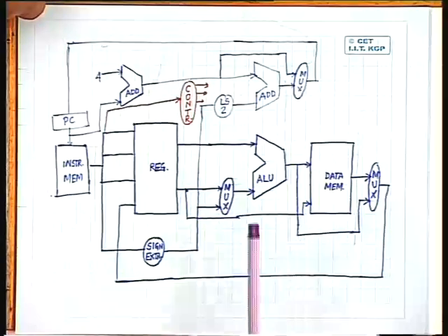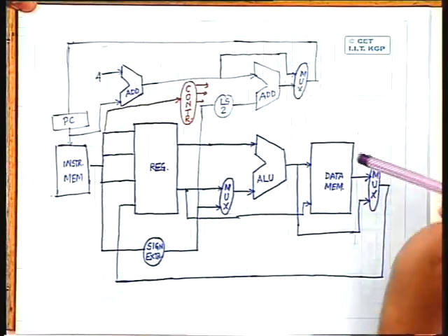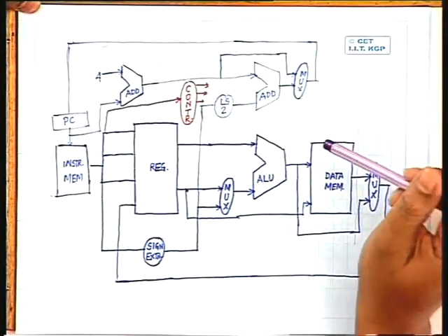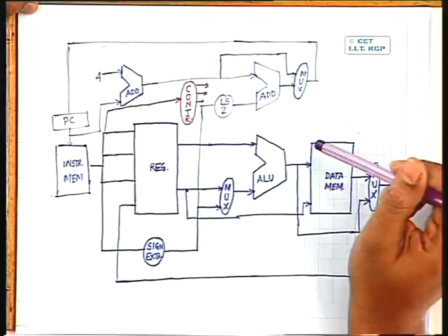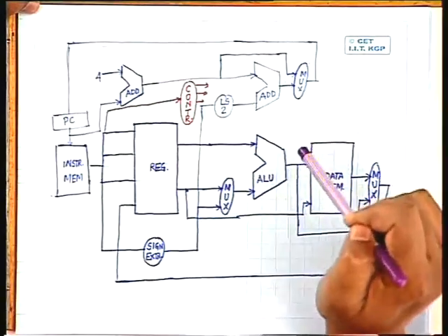We are discussing the MIPS processor architecture. We have developed one data path for single cycle implementation of instructions, and the data path, as we have seen, is like this. In this one, there are a number of data units which are duplicated. So when you go for single cycle implementation of the MIPS processor, there are duplicated data units. And we have seen later that the other disadvantage of single cycle implementation is that, on an average, the CPU performance will become poor.